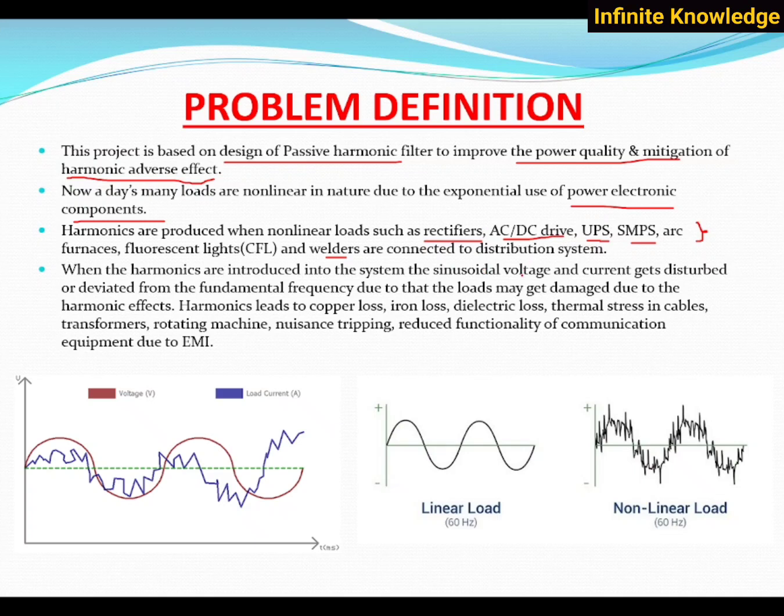In Maharashtra as well as some other states, the government is billing the industries by checking the harmonic level also, along with the kWh billing. So in other states also this implementation will soon apply. So we have to connect a harmonic filter if your system is creating harmonics. Otherwise, you will have to pay a high amount of penalty to your electricity supplier.